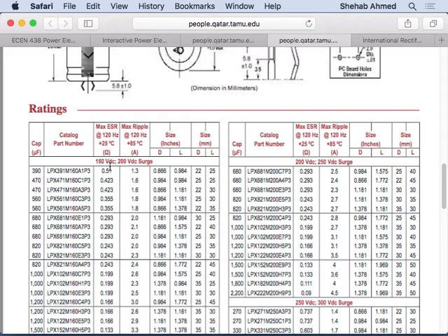Think of rectifiers, right? If you think of a 60 hertz rectifier, what was the full wave output frequency? The input frequency was 60 hertz. The output of a full wave rectifier looks like what? Double the frequency, right? These two humps that double the frequency. So they're at 120 hertz.